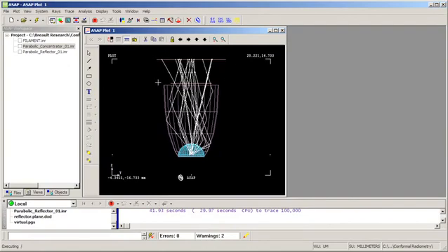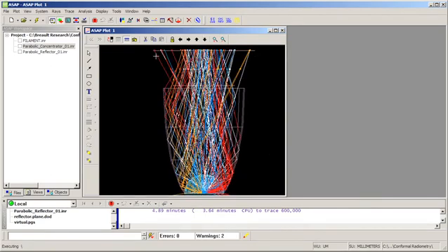Now in this case, these detector surfaces have been made to be transparent and actually have no effect on the resulting ray trace, but are still capturing all of the radiometric information that we've previously observed. So in essence, they're simply acting like monitors to the rays passing through. Now we can also see the rays being traced from the side surfaces of the LED die.